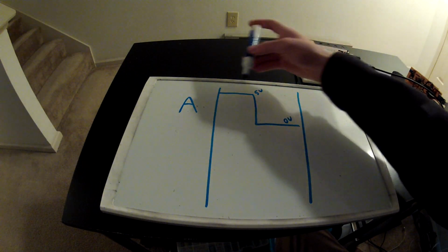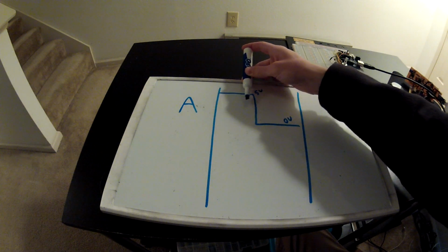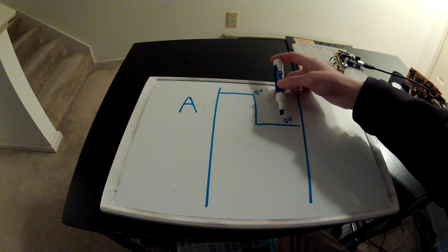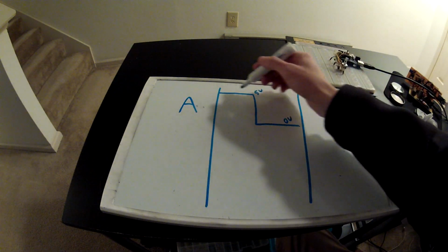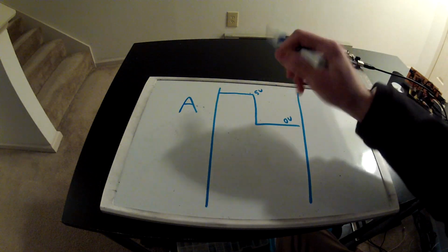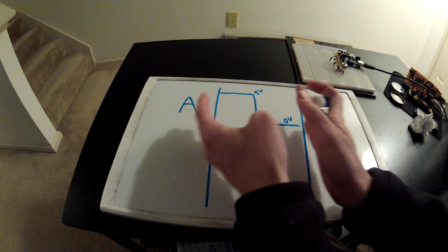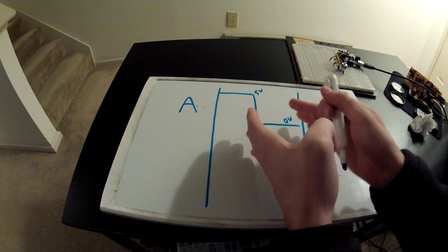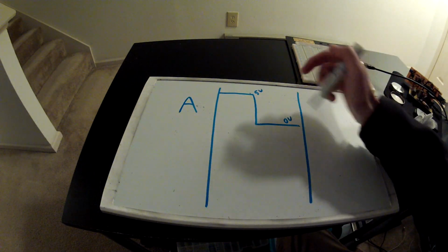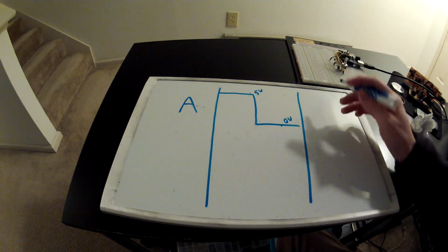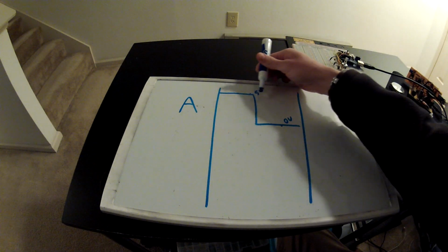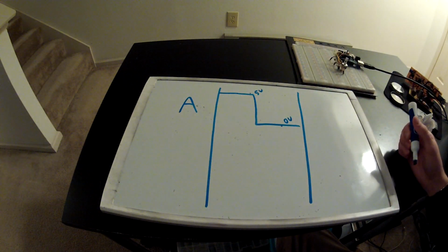So as you move through time, as you rotate the encoder, you'll notice that the A signal will go from high to low, and then this just repeats. I'm only showing one period of this, or one single pulse. So as you rotate it, the period of this pulse will occur faster or longer over time. So, right now it's stopped. It could be either at 5 volts or 0 volts. I don't know. It depends on where you left it. So as you rotate it, you'll get these pulses.